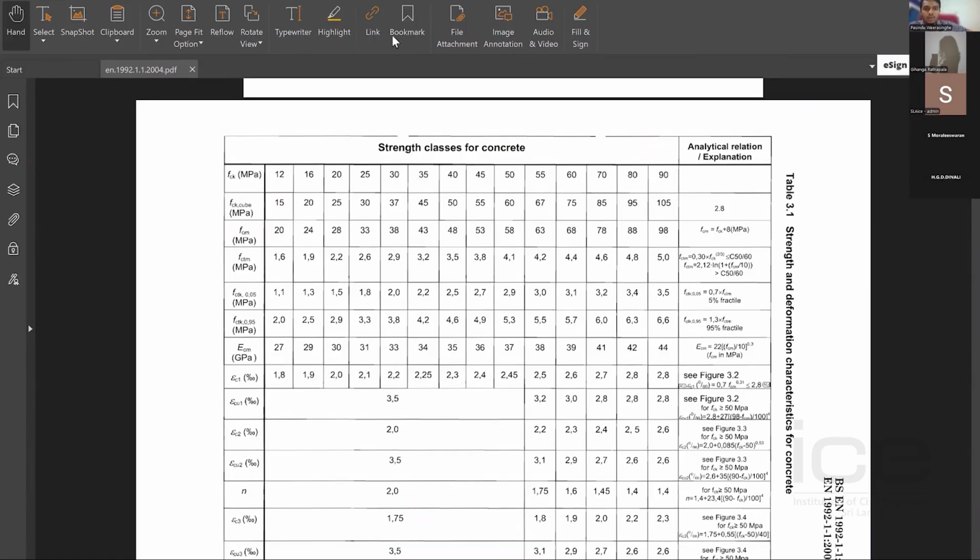If you are using Eurocode, yes, the limits are different, but don't do the design for both Eurocode and British code. If you're following the Eurocode, follow the Eurocode and do the design. According to Eurocode, we can now apply certain tension, because it is up to the designer whether to limit the tension to 0. But in the British code, different classes are there.